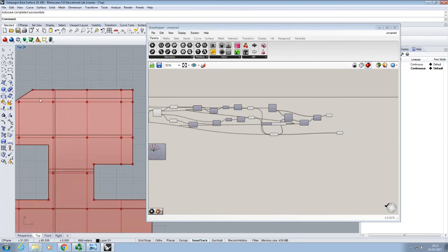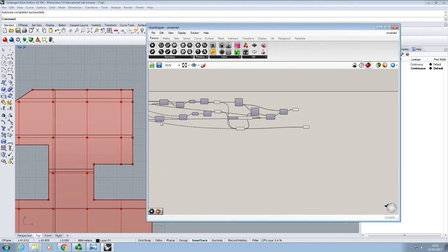So for example, around here I've got quite a few columns where I've got a set which is fairly close together, and by manipulating that we could probably come up with a better arrangement which had fewer columns, therefore less obstruction of the space, happier architects, everyone sleeps better. So to begin with, we'll try and optimize this based on the number of columns that we're creating.